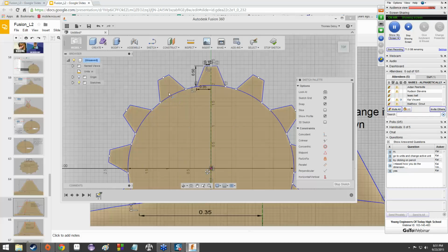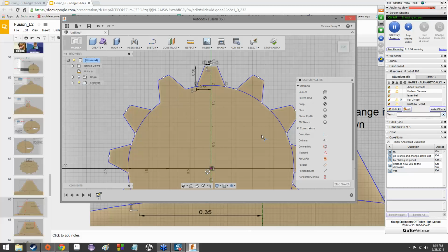And now mouse over lines. You'll notice that the lines that you mouse over turn red, but just the segments. So if we mouse over, say, the circle segment inside of the tooth and click on it, well, look at that, it goes away. So just go ahead and do that with all of the circle segments.